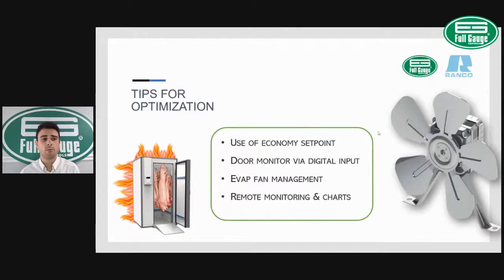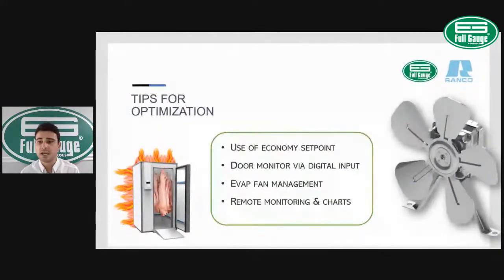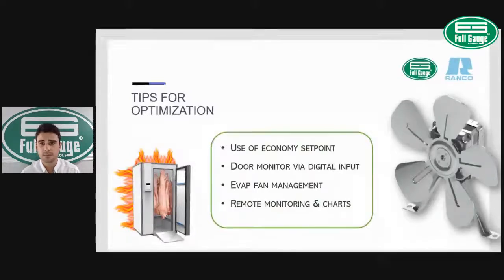And another nice way to optimize defrost cycles is with remote monitoring and control. By having predictive reports, by having the remote monitoring capability, you're actually able to better understand all your system variables and easily identify potential inefficiencies, raising possibilities of predictive actions, such as adjusting your defrost cycles, adjusting your defrost cutout temperature, adjusting different parameters for enhancing the system performance. So those are some of the tips we have on how to optimize your defrost cycles.